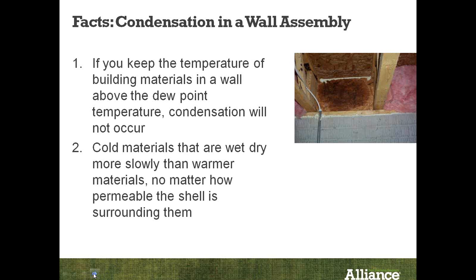Obviously, the dew point temperature in the interior environment is very dependent on the environment that the occupants create in the home. If the occupants live in the home, and they're in the home throughout most of the day, they cook a lot. If the home is fairly new and there's building materials that are still drying out, well, the dew point in that home environment will be a lot higher, which means that the building material temperatures have to be a lot higher also. So that's a main fact that I sort of want to focus on.